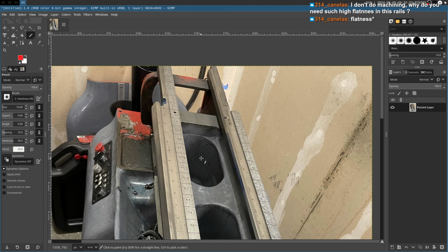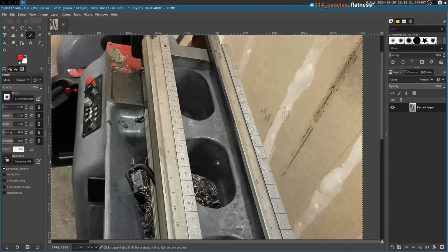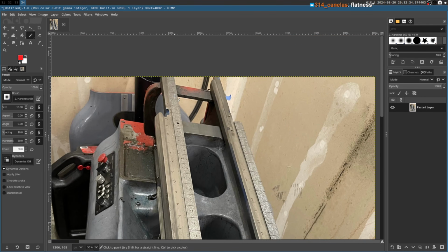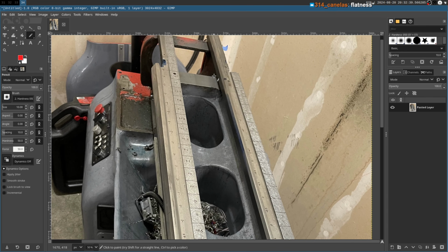So what I'm trying to do now is gain visibility into what these beds look like right now. These ways, in my opinion, and when I say in my opinion, I mean over thousands of measurements and my internal brain mapping of the lathe, I think are basically flat and within the same plane within maybe 25 or 30 micron right now.